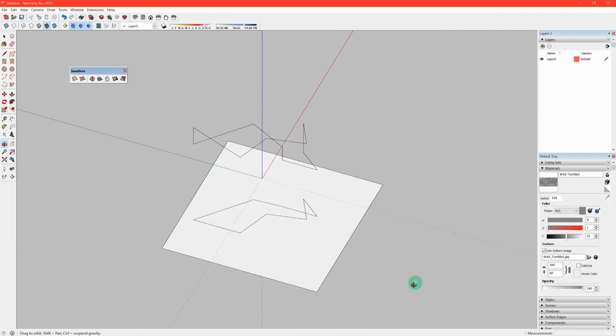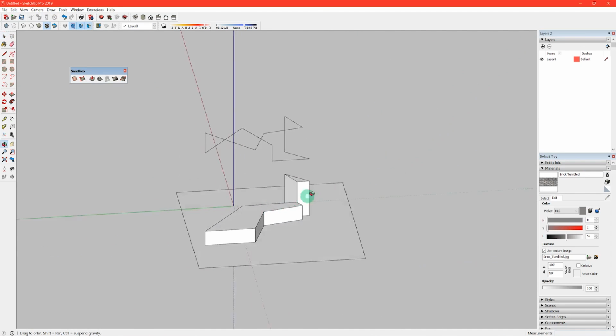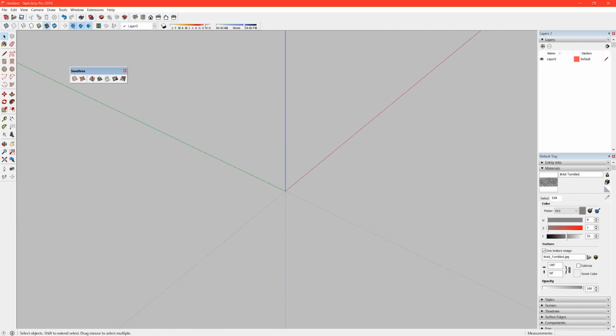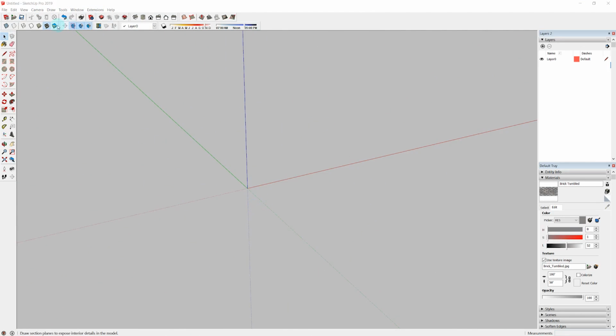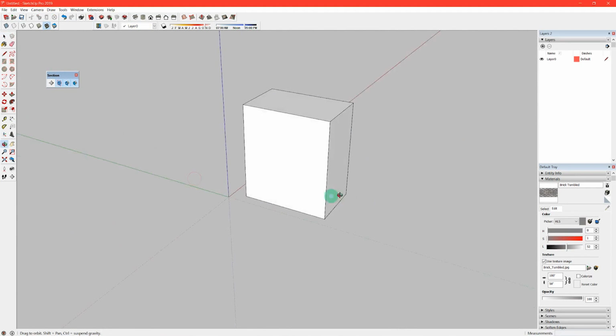And it'll automatically create faces on that plane. And so you can go ahead and extrude using the push-pull tool. So you can see I could quickly create a curb on a street or anything along those lines using the Drape tool.